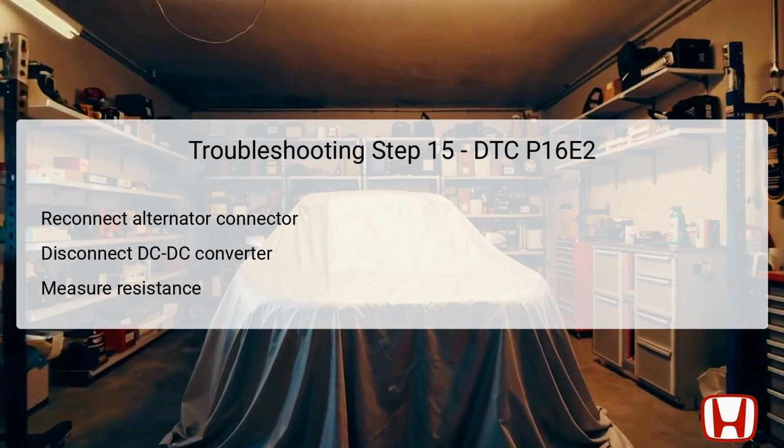Measurement will occur in the same method you've employed, confirming voltage at body ground through the testing points. Resistance of 1 megaohm or more will lead toward the remaining necessary diagnostic efforts. However, if resistance is lower than this parameter, it typically suggests the need for a recommendation toward alternator replacement.